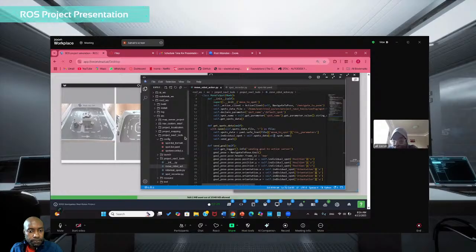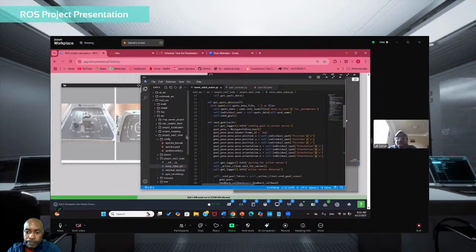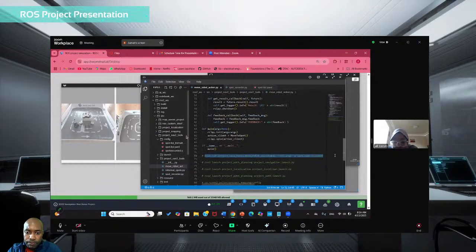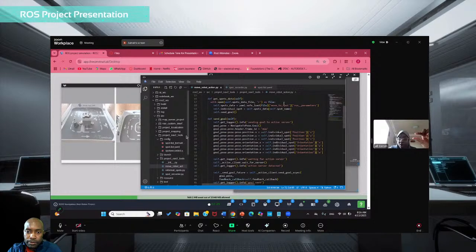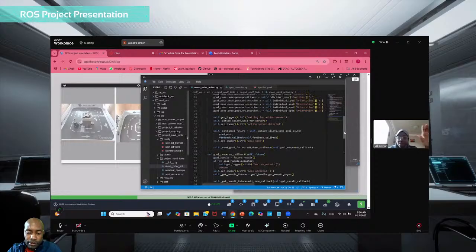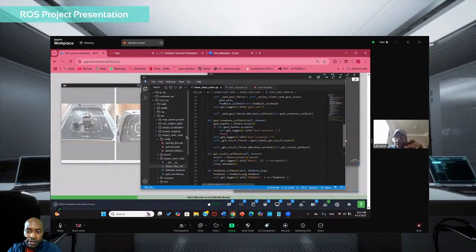It's reading from after the point of move to spot ROS parameters, right? And it extracts those positions that align. That's why in my command line I have spot name equal to corner one. So I've already specified the spot name, and it looks for corner one in the spot list, extracts those positions, and then publishes a goal to the robot to go to that particular position. That's how we do it from an action script.